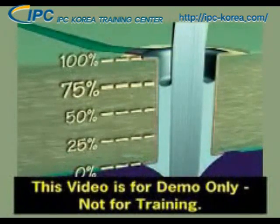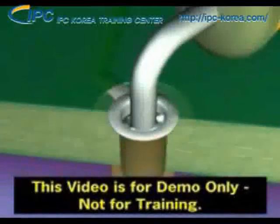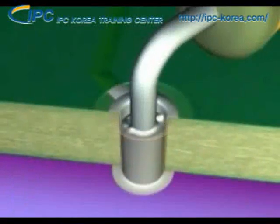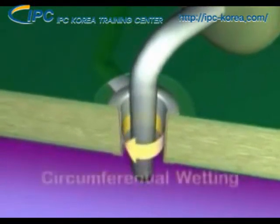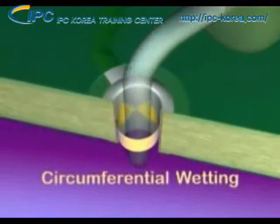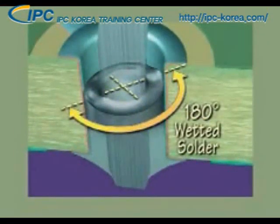Barrel must be filled with solder. The other parameter inside the barrel of a through-hole solder joint is the wetting of the lead and barrel. Circumferential wetting defines how far around the lead and barrel wall the solder wets or connects properly. The minimum requirement calls for 1/2 or 180 degrees of circumferential wetting present on the component side of the lead and barrel.